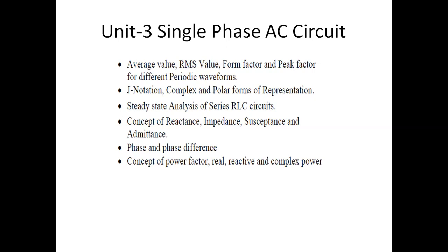So impedance will be in the form of A plus jB. The impedance is the combination of the reactance and the resistance. The real part of that impedance will be the resistance of that network, and the imaginary part will represent the reactance.